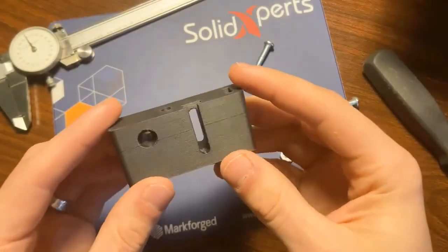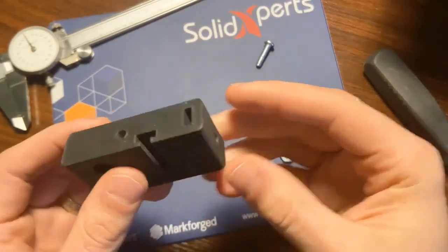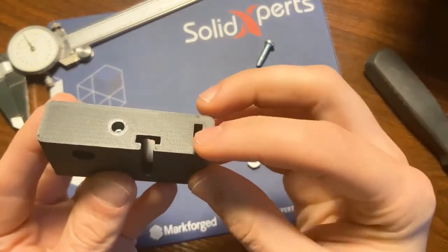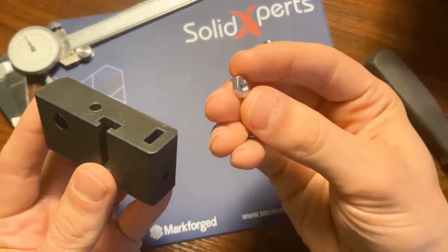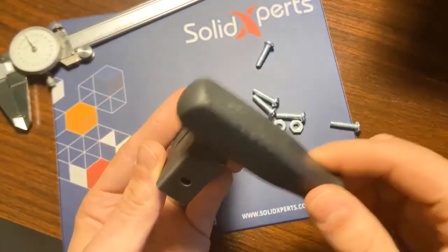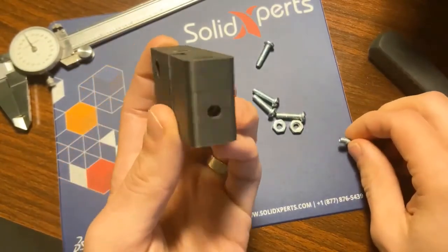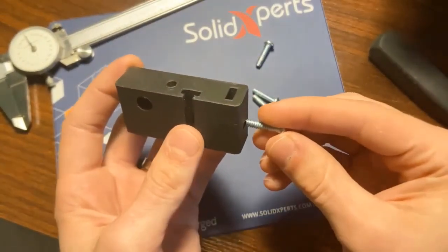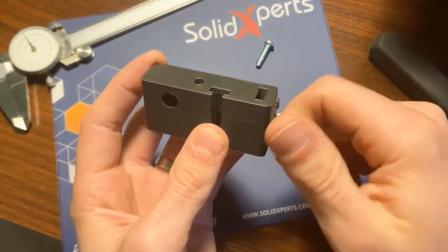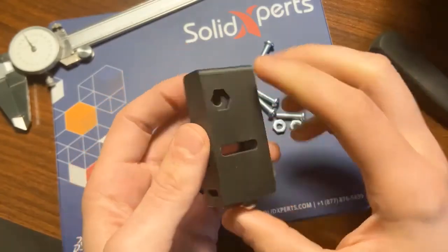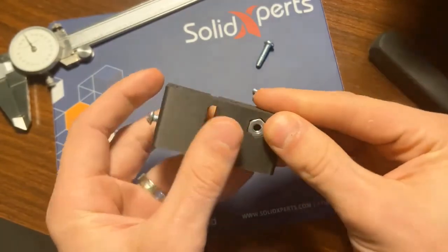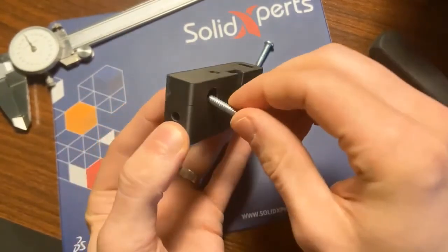So I have an example here of some of those embedded fasteners printed in 3D form, and I also have some floating fasteners as well. For an example here, we had mentioned that you can have a channel with a hexagon point at the bottom. You can place a small hex nut in there with the point facing downwards. Make sure it gets to the bottom. We can see the fastener inside of there, and we can add a small screw here. Other examples include having a countersunk hex nut, placing it in the hole, and using a fastener from the other side to secure it into place.